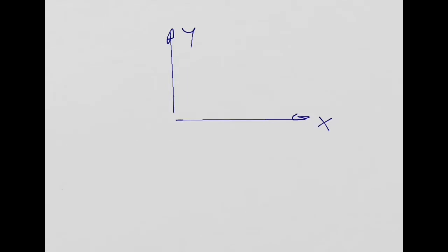So if you have a force here, like this one, and this is your position vector, r, the moment you will obtain will rotate anti-clockwise. And if you rotate anti-clockwise, you will have a vector in the z direction, the same direction as the positive z. Don't you agree? If you pull with this force, it will rotate about the z-axis anti-clockwise, so you will move in the positive z direction.